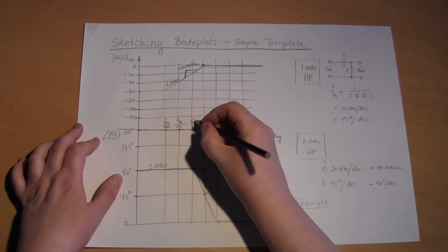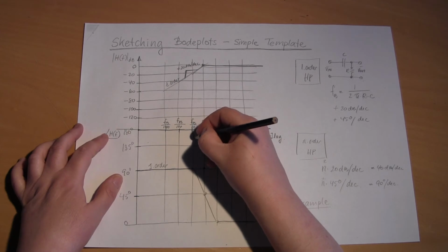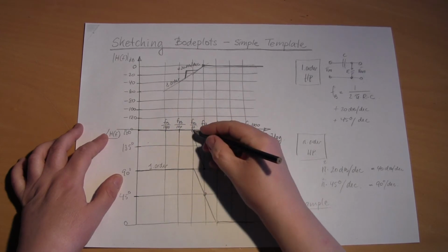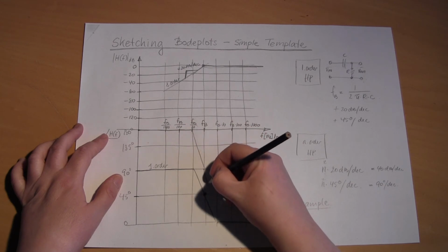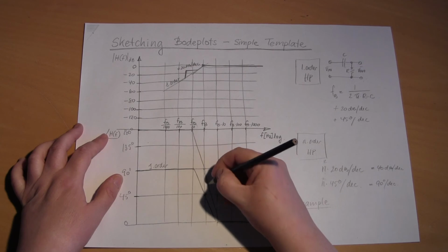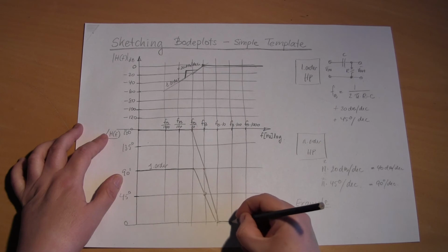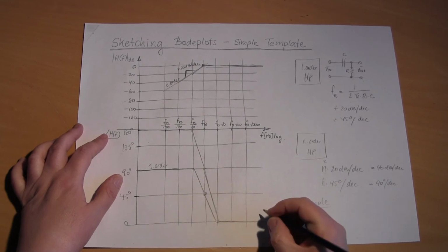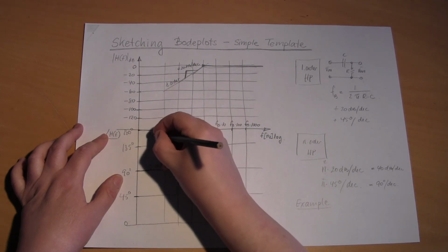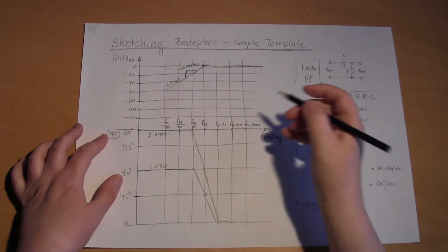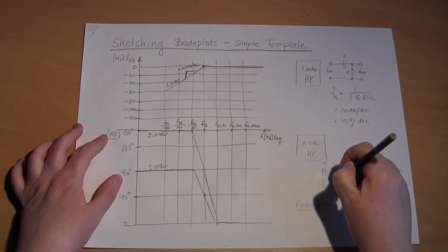And at a decade below the breakpoint frequency it will start phase shifting with now a slope of 90 degrees and continue until it reaches a decade over the breakpoint frequency, when it almost also will end up at 0 degrees. And that was the second order. What about the amplitude of the second order? Let's try to sketch that too.